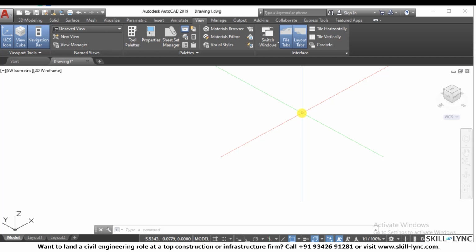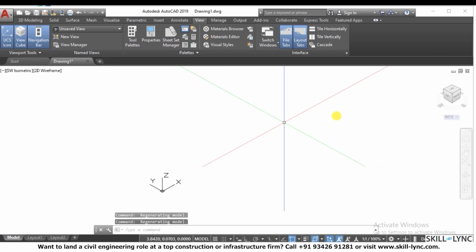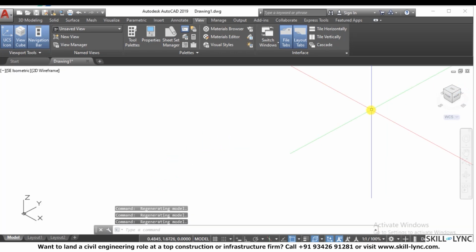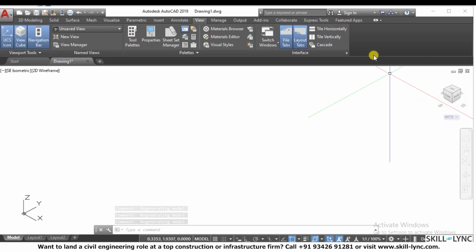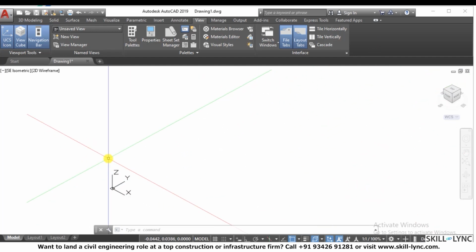Wireframe modeling is the basic modeling technique where we show different kinds of line work in different axes. A 3D wireframe model can be shown with line work. So let's create the default view over here. We can also change it if we want to see the XY plane facing our eye. So let's start. Now we'll be creating a cube of 3 units.